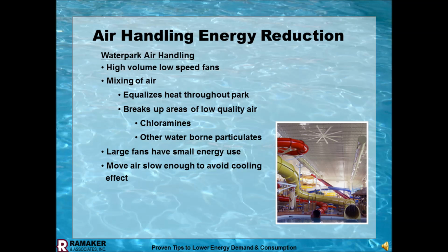The next step that we're doing, and this is on the current project our office has under design in Jay Peak, Vermont, is recycling some of the air. That comes back to what I mentioned about typical hotels where they have dehumidification. One of the standard brands is Dectron. A Dectron unit is just recirculating the air, dehumidifying, and when they dehumidify the air, they're just sending it back into the pool area with a certain percentage of fresh air.